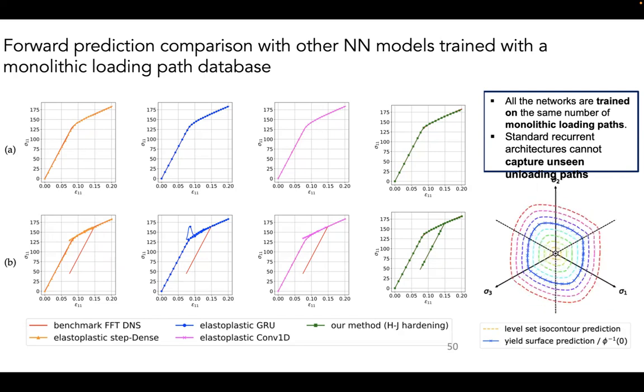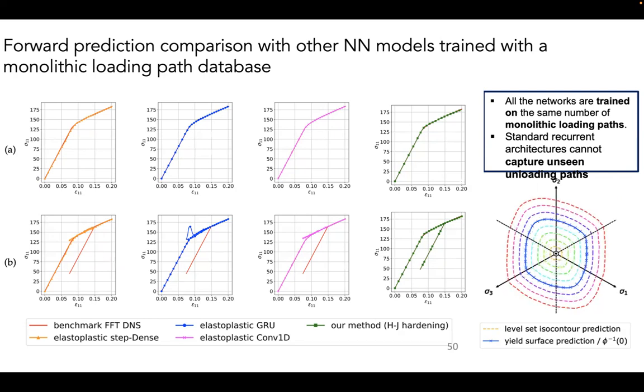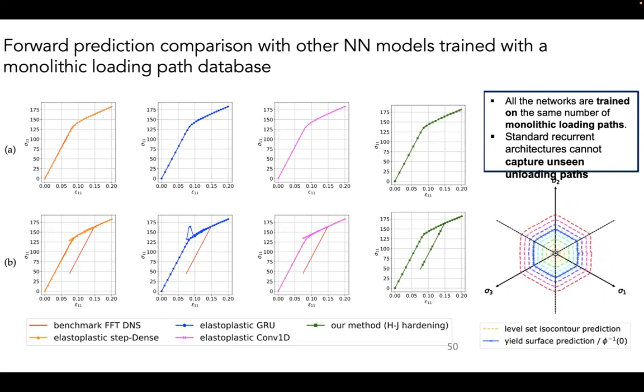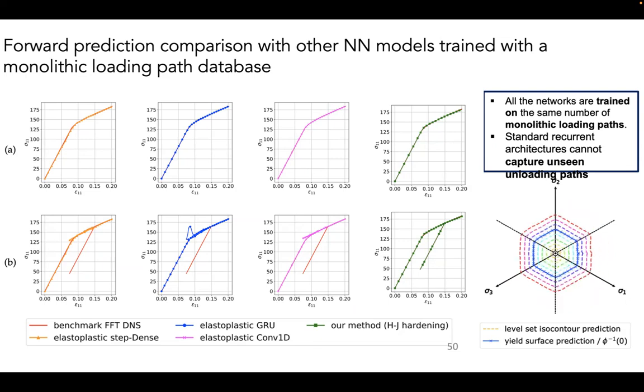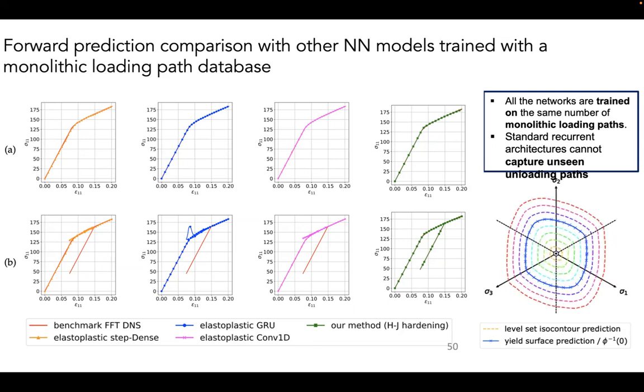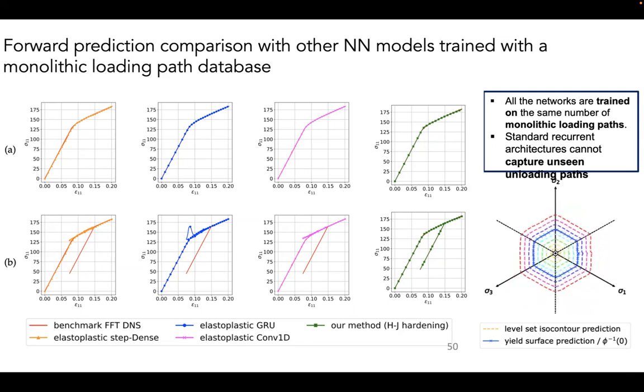For example, if a material is new, convexity has the following benefit. Let's say I have these two points that are in the elastic range. If I have a non-convex yield surface and I draw a straight line between them, a linear combination of those elastic states will suddenly yield, which is not good and creates complications.